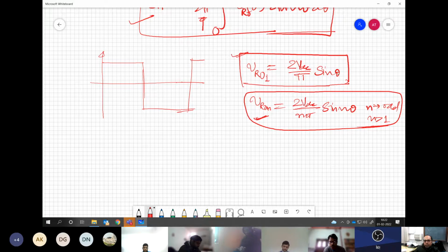Now let us say that you have to run your motor from an inverter and you are generating this kind of voltage. So you are bound to have a fixed voltage unless you change your DC bus voltage. You understand this point? You have a fixed fundamental component which is coming like this. Notice that this is VDC by 2 and this is minus VDC by 2.